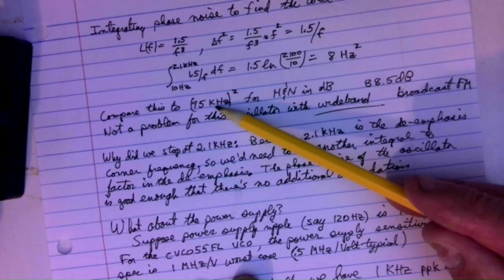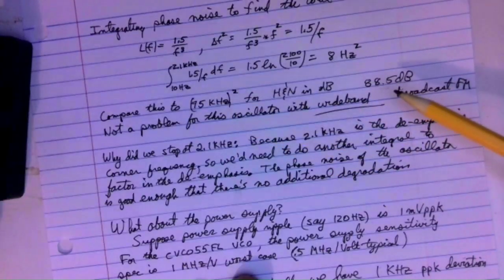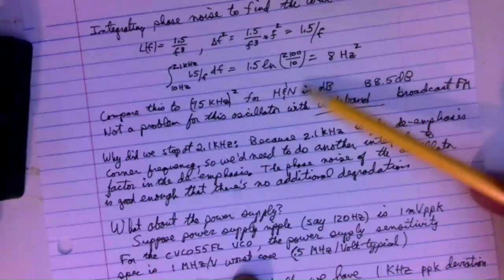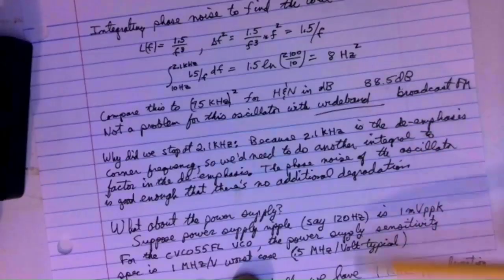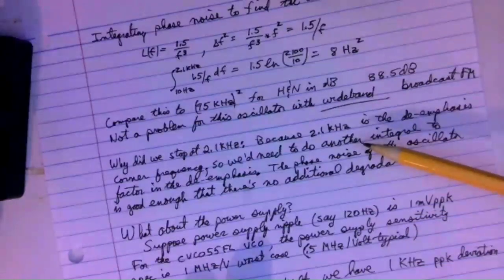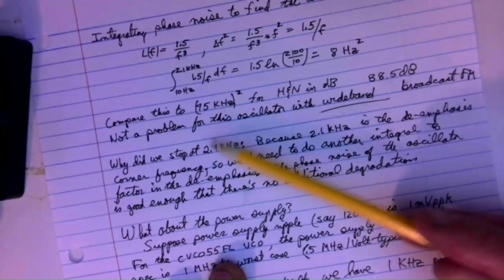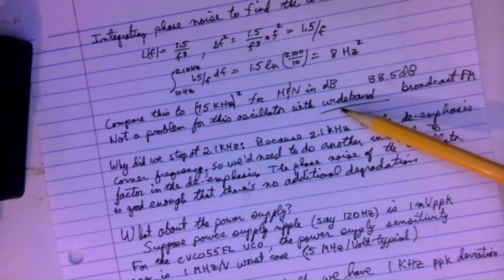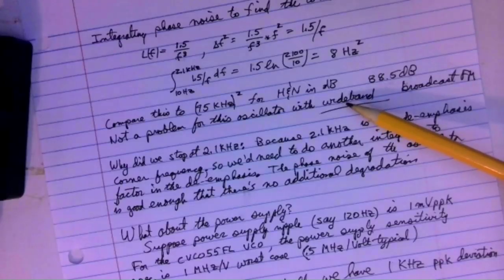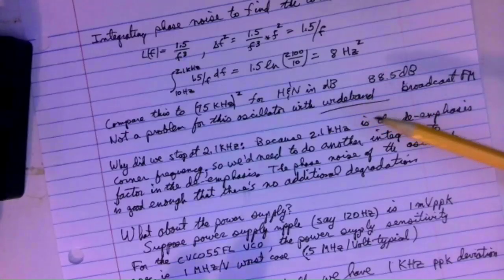Now you're not going to be getting 8. You may have the same oscillator phase noise, but you only have 3 kilohertz deviation for your reference. You're not going to be doing so good. But it's not a problem for this wideband FM. That's why we have wideband FM, because the larger deviation gives you a larger audio output, and all these little noise sources are less significant. Clicks and pops, everything's less significant compared to a large audio output relative to a small audio output.